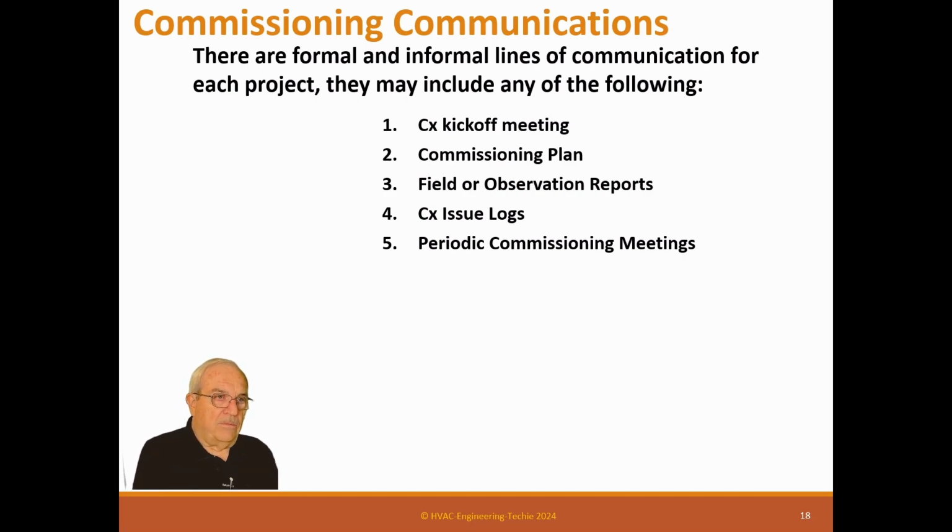This is another thing about difference between process and technical commissioning. In the standard 110, we actually state that a project, when it's done, there should be no unresolved issues on the issue log. They should all be resolved. That's easier said than done. Process commissioners say that's not their job. Their job is to find the issue, not to make sure it's completed. We think that's totally false. And I've seen projects that have 30% of the issue log has never been resolved or even addressed, and that's not acceptable. So we actually tell people that every item has to be resolved.